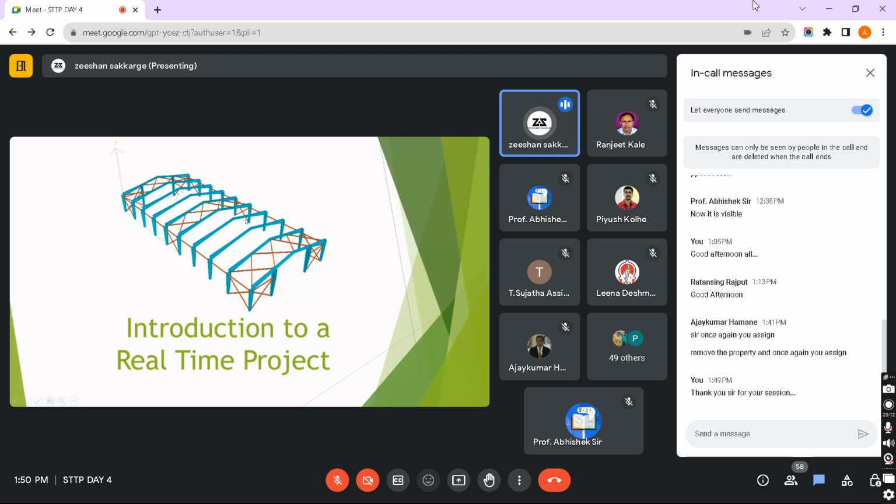Right now in our comparison example, we have only considered a simple load of 15 kilonewton per meter, just to make you understand the difference between your standard frame and PEB frame. But in reality, we have dead load, live load, wind load, earthquake load. Also, we have wind loads coming from all four directions, and how these combinations are done. We have loads on our purlins. How all these loads are modeled, I was not able to show you because of the shortage of time. But what I will show you is the final output.